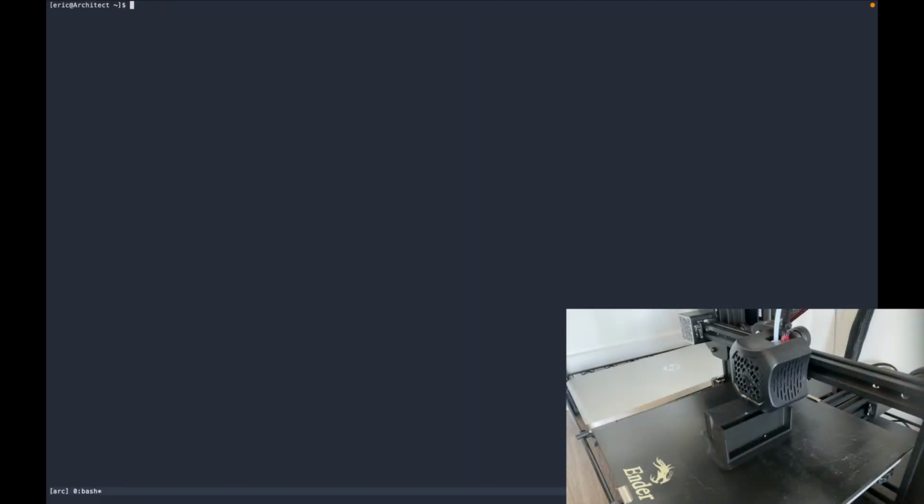Okay, so before stepping back through the G-code commands, I need to make sure that the XY coordinates are reset. So currently it thinks this is position 0, 0, so I need to give it its true 0, 0. And I need to be a bit careful how I do this because there is an object on the device. So what I want to do first is tell the Y position to move to 0. So I'm going to send that to the device, not to my output.